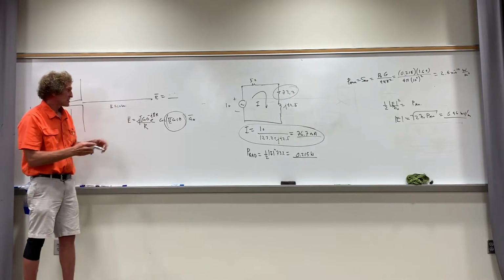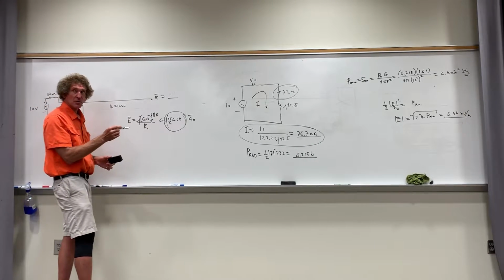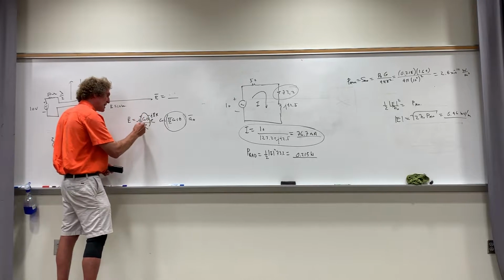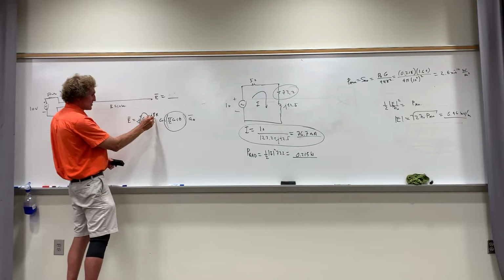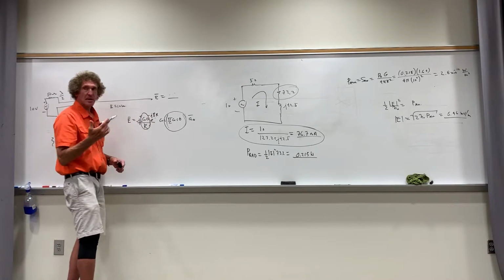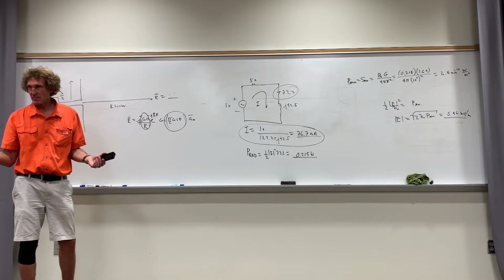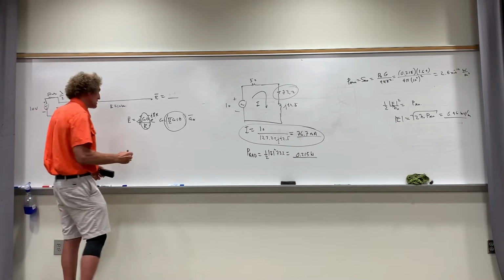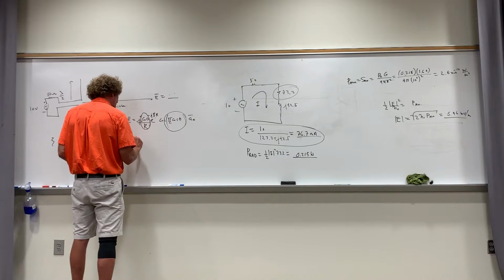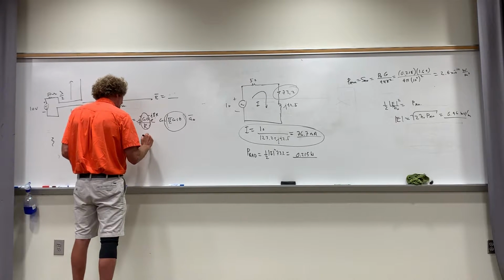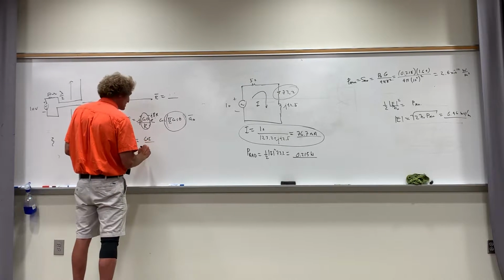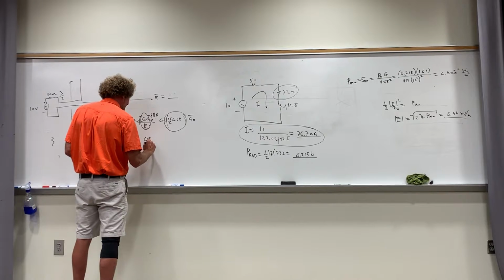That means the only thing I have to calculate in terms of magnitude is just 60I over R. The magnitude of j is 1, the magnitude of e to the minus j beta R is always 1, it's just 1 at some angle. So the E field can be gotten as 60I over R, which is 10 to the 4th.